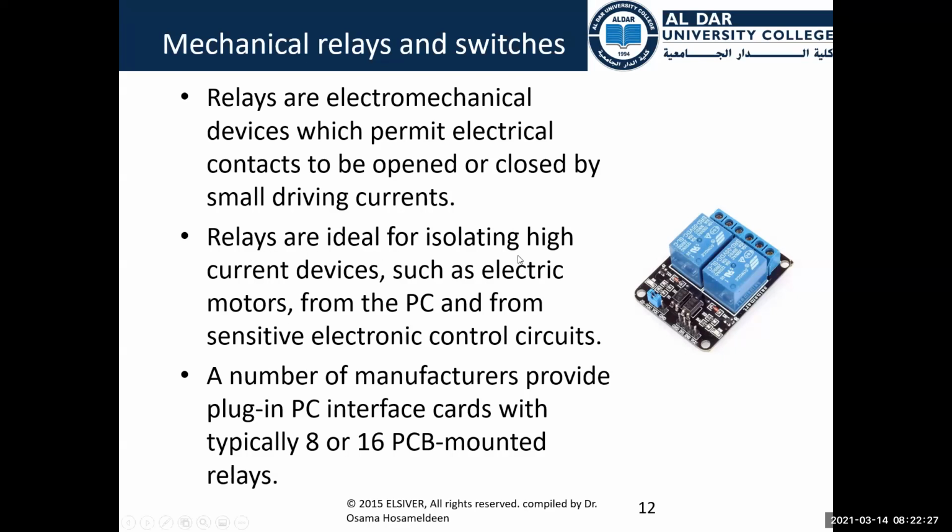So relays are ideal for isolating high current devices such as electric motors from the PC and from sensitive electronic control circuits. Because if they are used directly with the PC, the high current devices, like motors, may affect it. If I connect the motors directly to the computer, maybe the motors will burn the motherboard of the computer. So relays are important. Even some computers have built-in relays used for protecting the devices or protecting the PC.